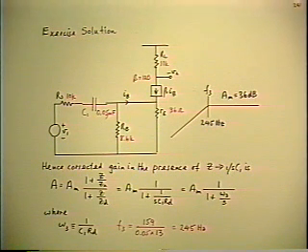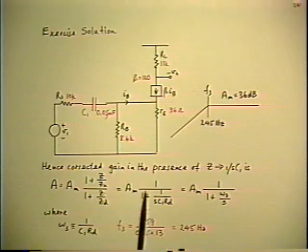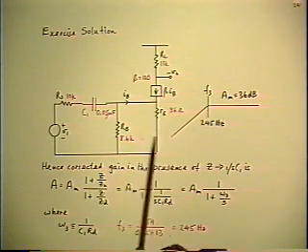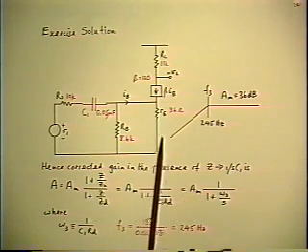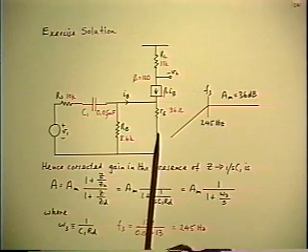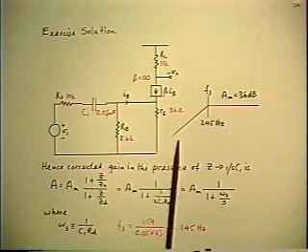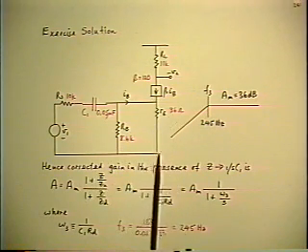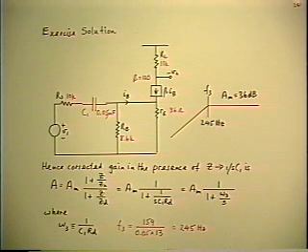The only case where it didn't was the one where the extra element was a parallel R and C, in which case the driving point impedances were still resistances because the reference circuit was resistive, but the extra element was an impedance and not a reactance. And so that required one more line of algebra to get the pole zero form.